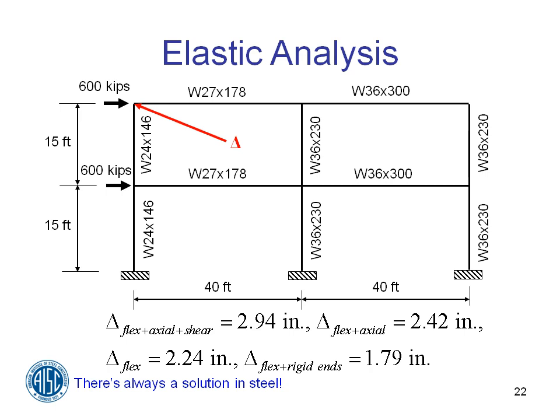In steel design and analysis, a rigid connection is what we have when we model the beam from node to node, center line of joint to center line of joint. That would be a rigid connection, but not a rigid end offset. The rigid end offset says, okay, from that point to the face of the column, we have no deformation.